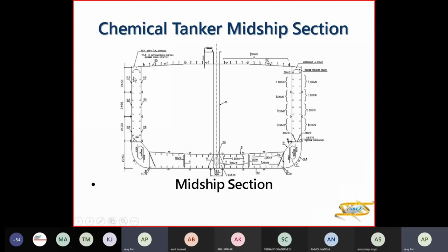So here you have longitudinals in the double hull. You might have stringer plates also here. That's a stringer plate here. And the double bottom tank is longitudinally framed. So this tanker is longitudinally framed. Your longitudinals will be on the deck, girders will be on the deck, and the remaining longitudinals will be in the DB along with your girders in the DB.